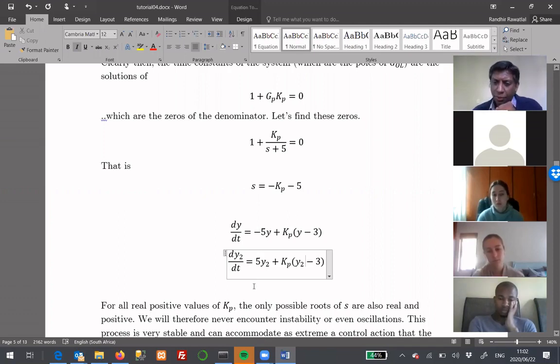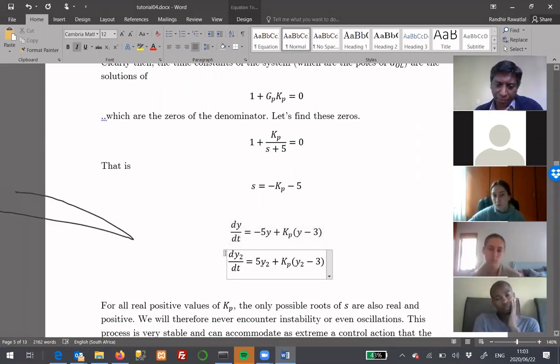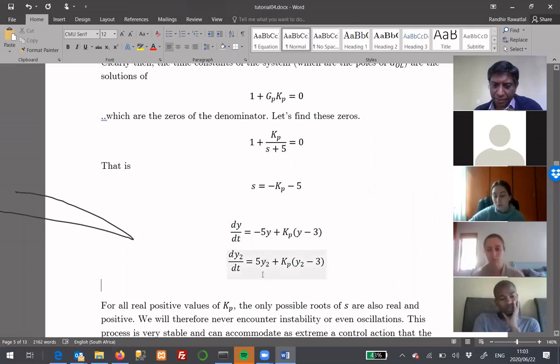And in fact, that was a question that was asked last time. I can't remember, I think maybe Jenna, you asked the question, what about processes which have instability in them? So this is an example of an unstable process, right? The first one was stable. That was just zeroing out, right? It was undesirable, but we don't think of it as unstable. It's not running away to infinity. This second problem with the positive 5, that is an unstable process. That's going off to infinity.